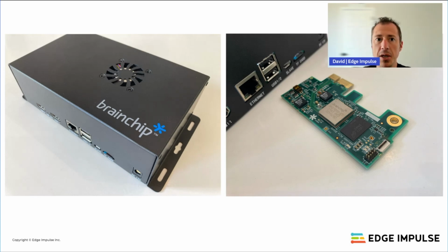Even better would be to build a custom PCB and wire the Akida processor to the host CPU directly via traces. Or if you really want to lower the power envelope required, BrainChip also licenses the Akida IP. You could use off-the-shelf ARM Cortex-M cores and spin your own MCU with integrated Akida cores and build a device that lasts for days or weeks on battery power alone.